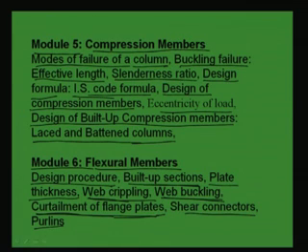because we will see that the moment is varying throughout the span of the beam. So, we generally design the member for the maximum moment, but that maximum moment generally happens at mid span, and at other places this moment reduces. So, there we do not need that heavy a section. So, we can reduce the section by the use of curtailment of plates.